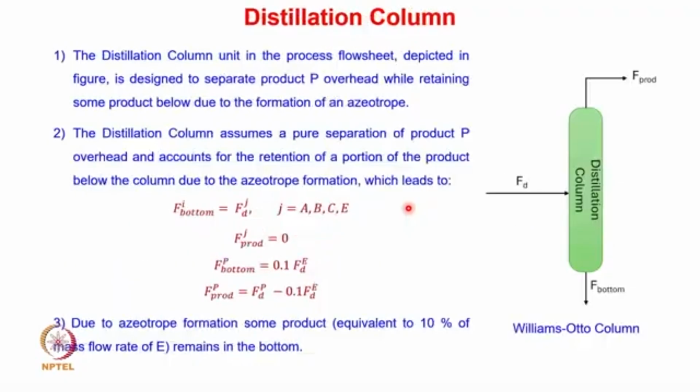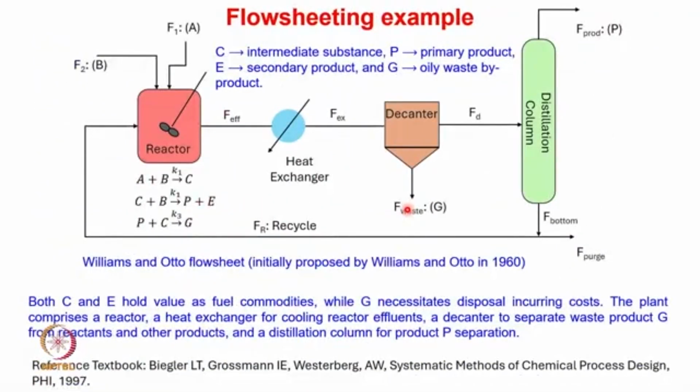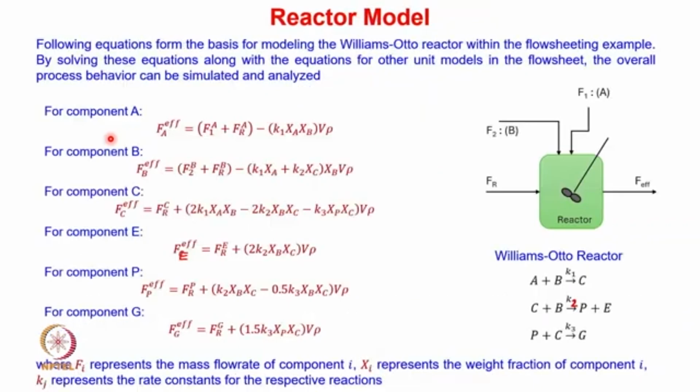Very often we select the input to the reactor as a tear stream, and that is what we have seen in the previous case. Also, you can see that we are assuming the inlet concentration of the different components in the recycle stream. So clearly the inlet to the reactor is what we are considering as a tear stream, isn't it? We are breaking this loop somewhere here, and that is why we were able to do the calculation sequentially in a forward direction, isn't it?